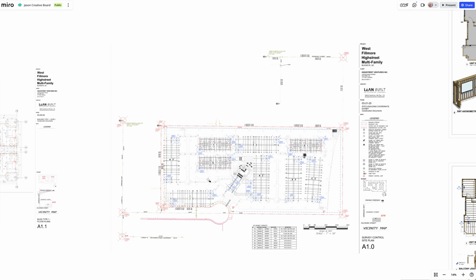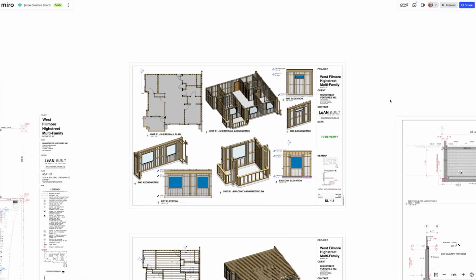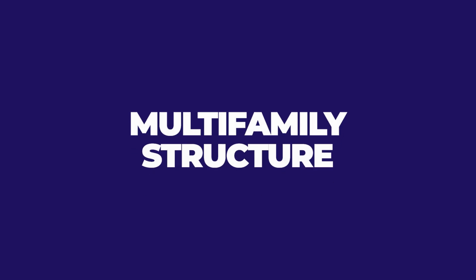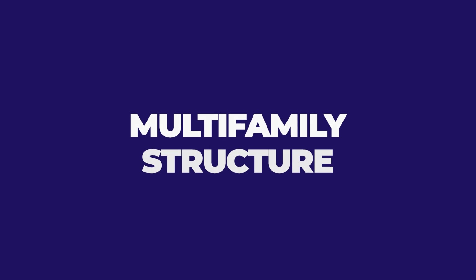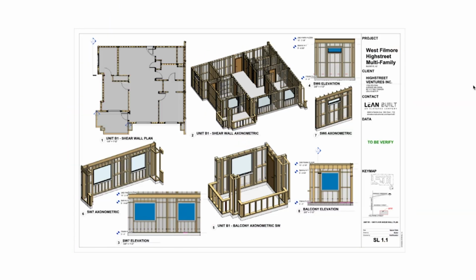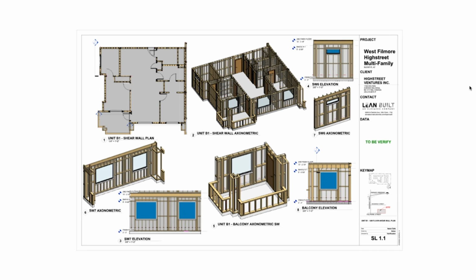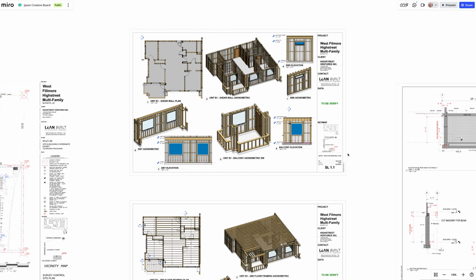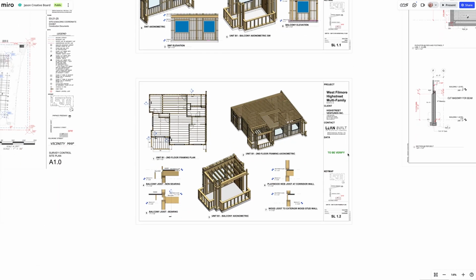So super cool. Let me give you another example where a lift drawing is required for a building like this, no matter how familiar you are with it. This multifamily structure has different structural details, different types of hold downs, different anchor bolts, post-tension slab on grade, and there are different details in here that we need to know. So from a QC perspective, we literally went through here and modeled 2 units all the way up through the structure so that when we're out there QCing everything, we know exactly how it's supposed to go.